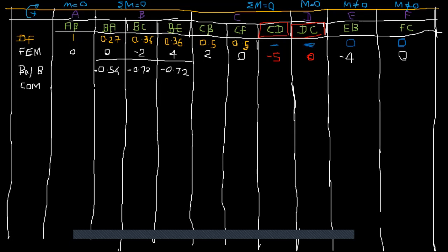A is a discontinuous joint, so you don't give anything. Continuous to discontinuous, you don't give. But the other way, discontinuous gives half to continuous. So that's fine. BC is continuous. Its neighbor is CB in the same beam. That's continuous to continuous, so you should give half to here.